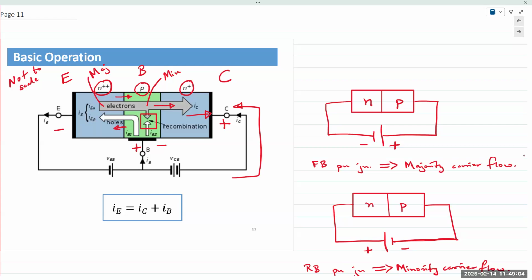So yes, depending how the base voltage, let's say it's an AC signal, goes up, goes down, goes up, goes down, depending on how it changes, the current flow would change. And then the collector current would change. So absolutely, you're correct, right? That's the basic fundamental principle. Current flowing between the collector and the emitter, and then the base controls how much is going to flow through.